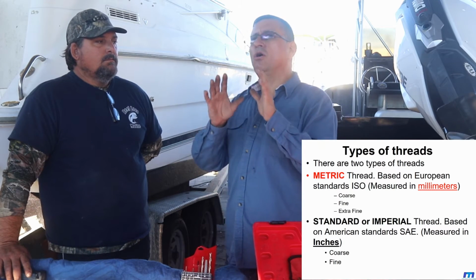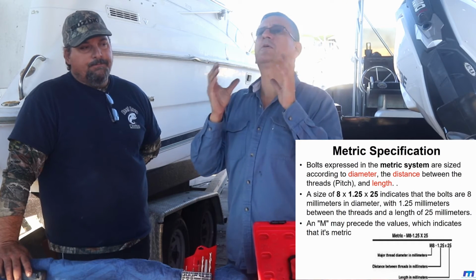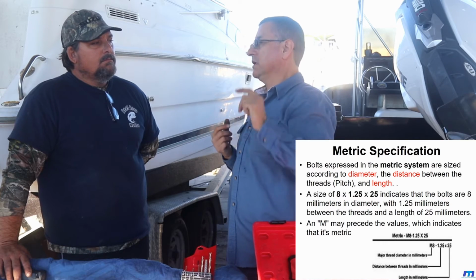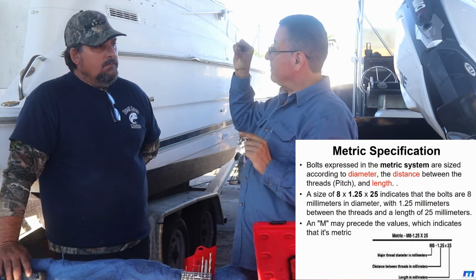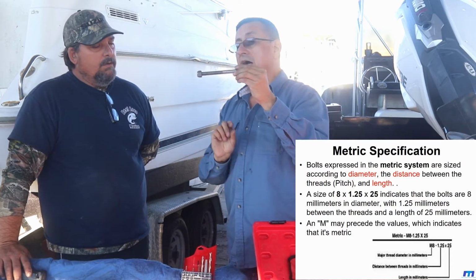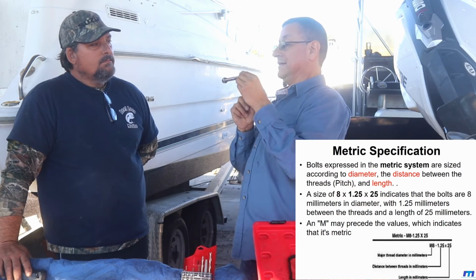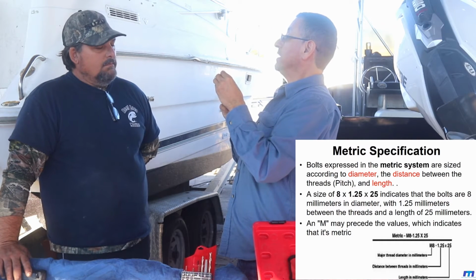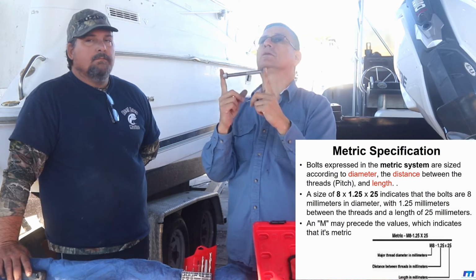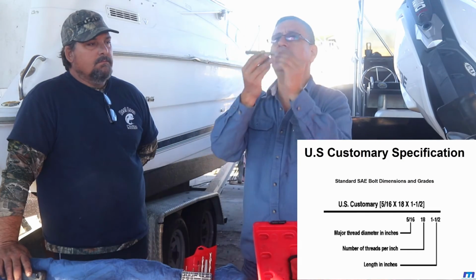In metric, both of them have three digits for the correct specification. The first one, we are going to talk right now about metric. The first one is the diameter. This is metric, and this is the diameter. This is the first digit. The second one is the distance in between two consecutive threads. And the last one is the length of the bolt. That's for metric.